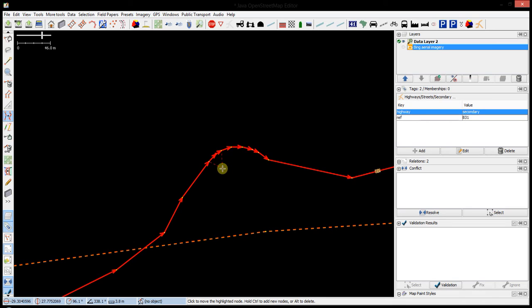If you'd like to remove some nodes, hold down the Alt key, so that's ALT, and again you will see single nodes selected in between lines. So all you do is while you have the Alt key pressed, you simply click and it will remove excess nodes.